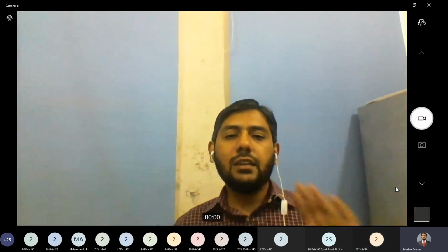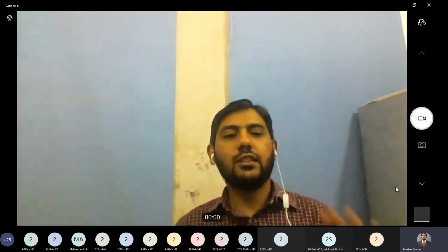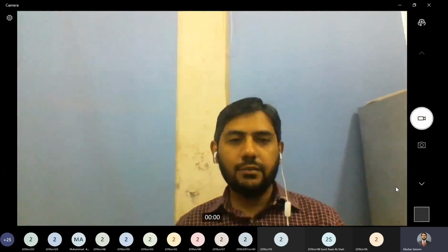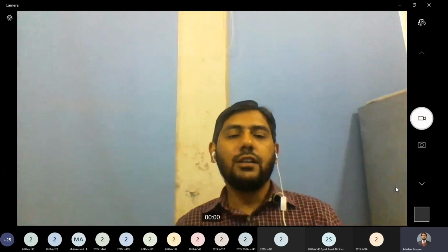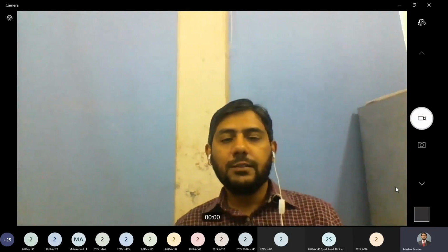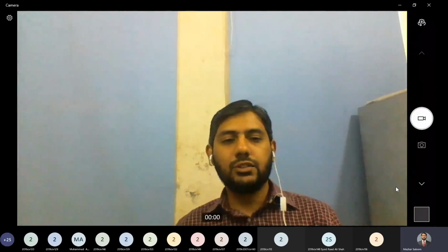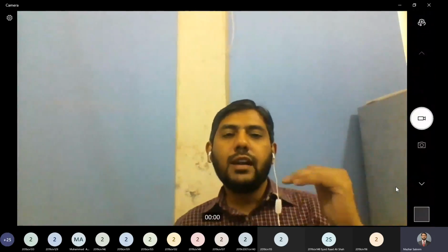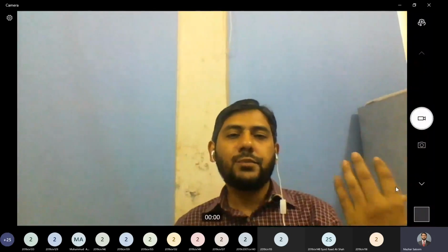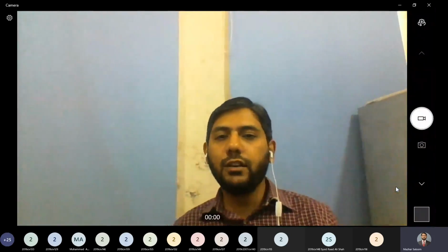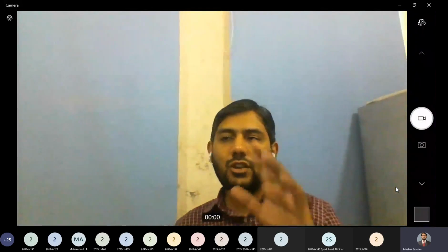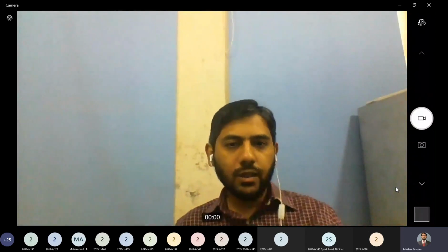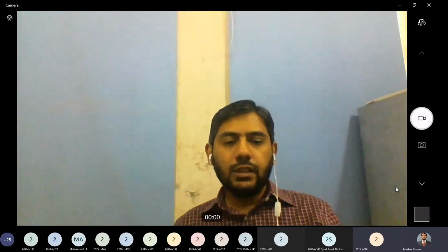But this device can be used to measure inclined distances and horizontal distances as well. In case of beams, normally the deflections are vertical, but we might have some other component, maybe some truss element present in the vertical plane. It may be inclined or it may be vertical, and in that case, deflection will not be vertical. It might be horizontal. So even if that's the case, we can change the orientation of this device and we can measure the horizontal deflection as well. Okay. Thank you, sir.